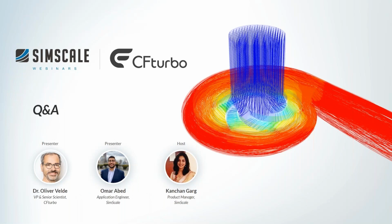Thank you for that, Oliver. On the simulation side, just about all the kind of parameters that you can modify can be parameterized to an experimental run within the simulation setup side. So if we're interested in multiple different duty points or flow rates, if we're interested in looking at multiple speeds of the rotor, we can parameterize that input as well.